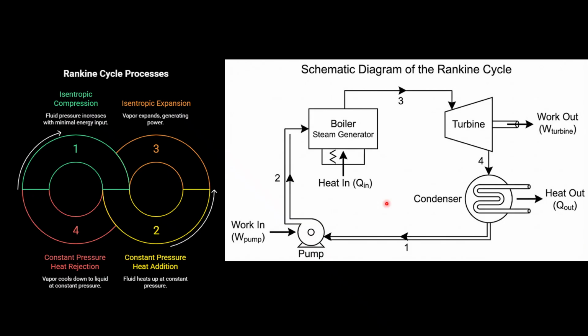From state 1 to 2, the feed water enters the pump. The pump's function is to increase the pressure of the liquid water. Since the water is incompressible, the pump requires very little work input, and the enthalpy rises only slightly.